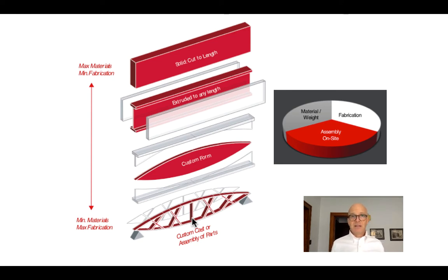In the extreme case, you could get a beam so long that it couldn't carry its own dead weight. And what we're doing here is we're finding ways basically not to make the beam necessarily stronger, but to make it lighter, to take away weight that we can then use either for live load, or we can actually use it to extend the beam's working length, the workable length that it can span on its own.